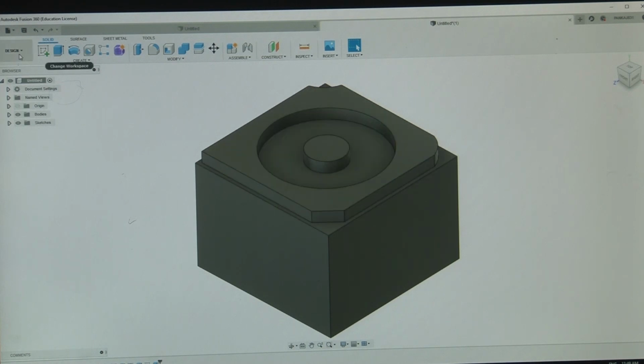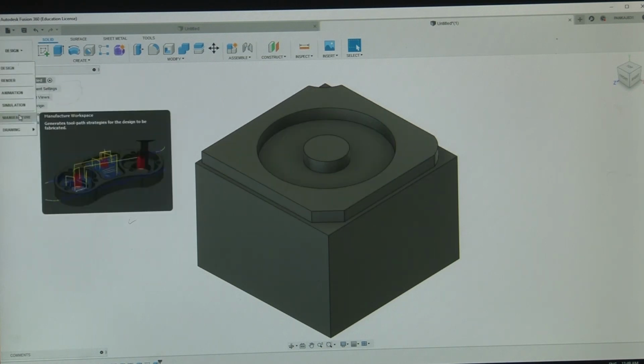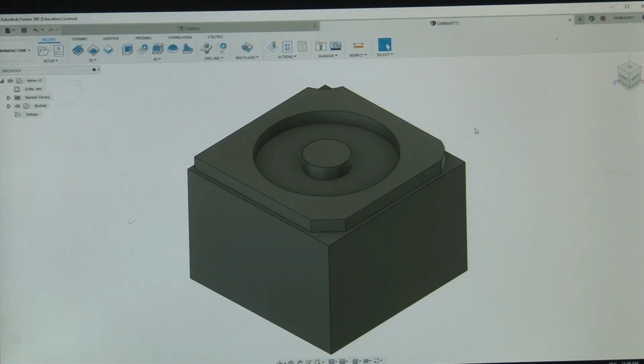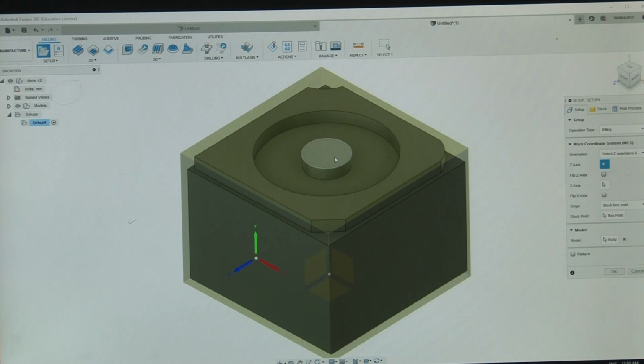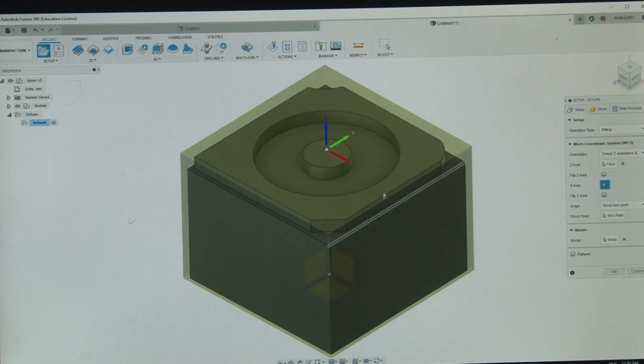So, you go to manufacturing. This is the workplace, then this is the XY coordinates or ZX or ZY. According to that you find out what the coordinates are, select the coordinates in the manufacturing area of this program. Then this box point will be placed here. So, you put the system of axes at a certain point which will be the 0 point.